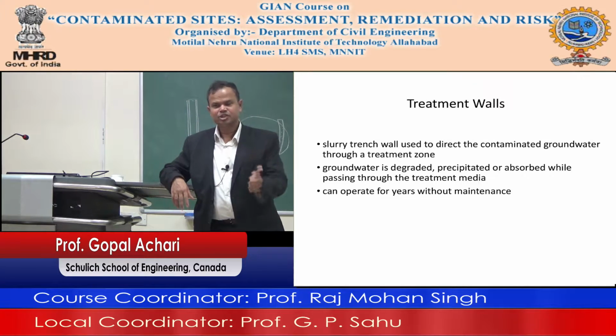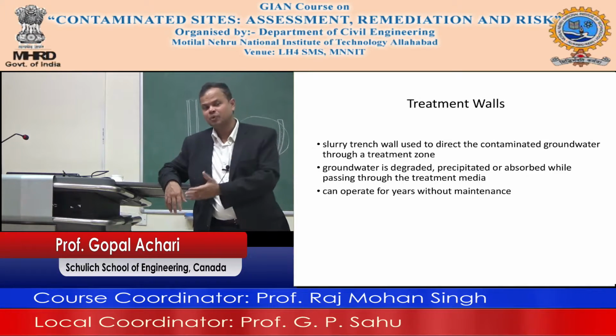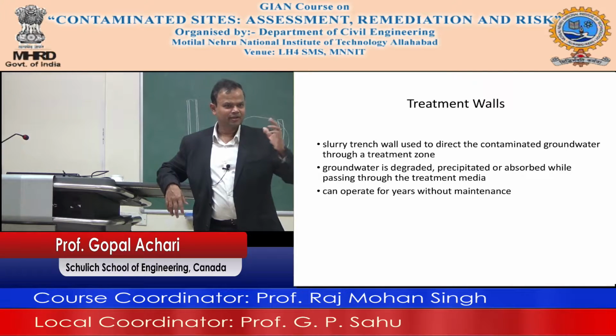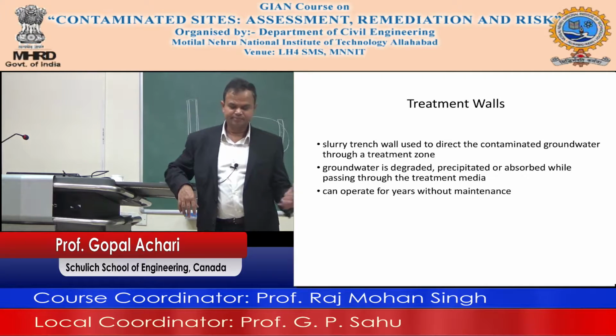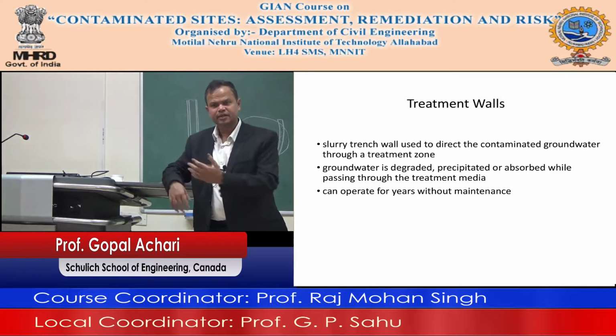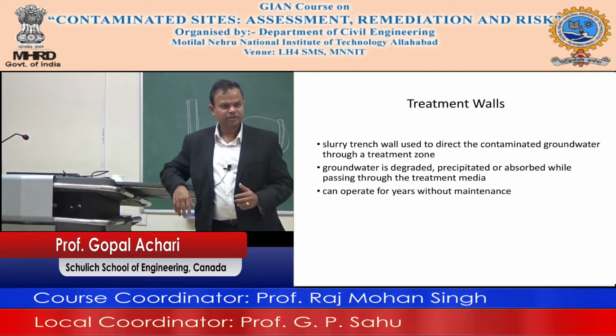And remember, the geology of every single site is different from every other site. Geology is different, soil characteristic is different, everything is different. So some may work better, some may not work as well. You never have one size fits all. In some places soil vapor extraction is great, some places maybe you have to use chemical oxidation, maybe you have to use multiple techniques at a particular location.